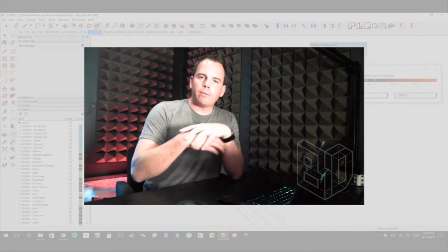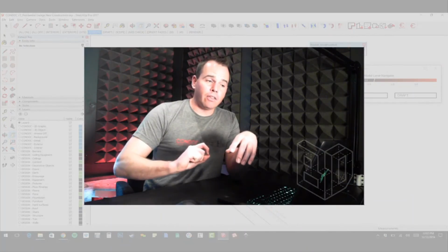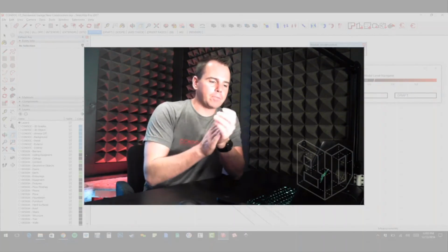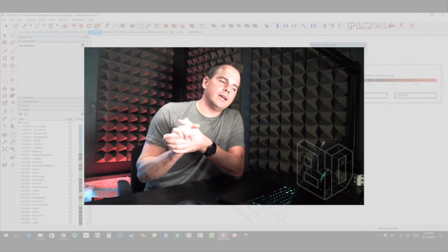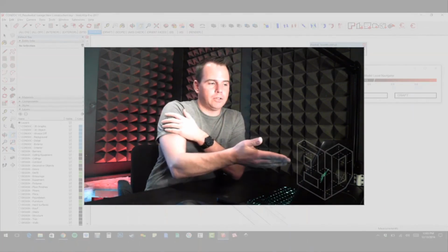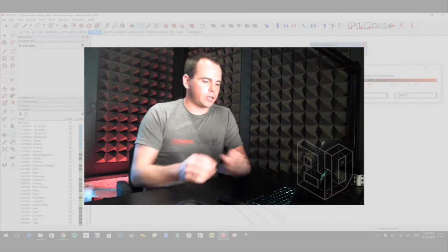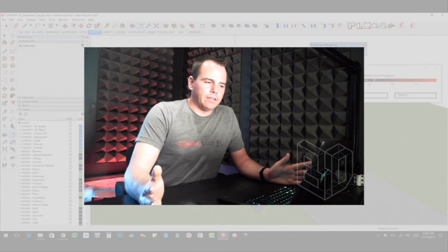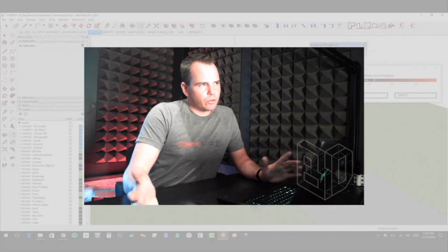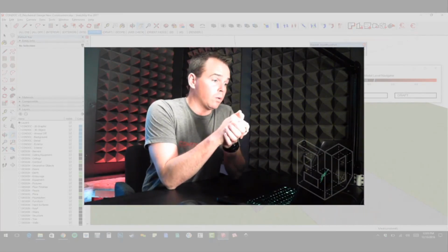So what happens is when you run the plan generator, you create a roof plan. You could then go back in and say on the light scene, you want your structure to be on, and then it would just show up as this 2D graphic. So that's kind of the long and the short of that. That goes with anything. So framing plan, floor framing, roof framing, you could set it up in this way, and that would work well.